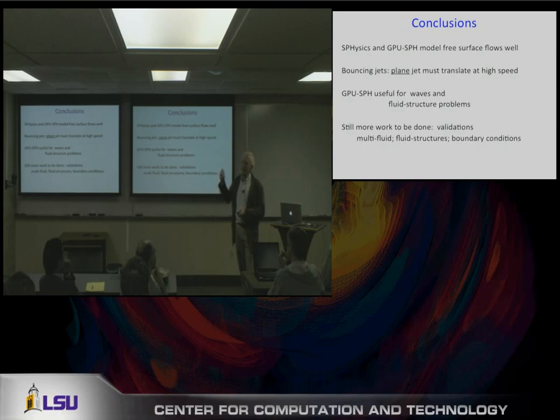But we actually now have new features in the model where we can ask for surface particle position, so you get the surface layer, and that works very well. The other thing is we have something called test particles, so we can put in Eulerian points. This is a Lagrangian model, so all the particles are moving, but we put in fixed points, and then we do that SPH averaging at fixed points, and so we get data files that are measurements at a point. The next thing we're going to do is have a wave gauge, so you say, I want to know the water surface behavior with time at a fixed point, and that'll be the other measurement particle we have.